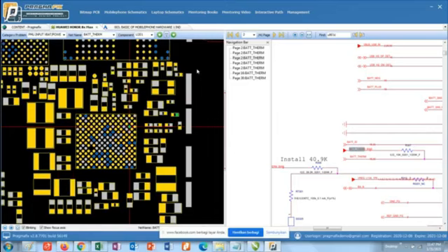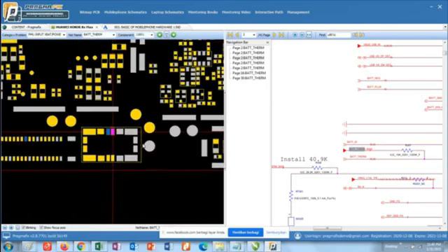At that time the NTC thermistor is connected to the ground, because NTC means negative temperature coefficient of resistance. As the temperature rises, its resistance drops, so it will be more connected to the ground. So the battery connector's temperature line will be connected to the ground in the battery. That's the meaning of NTC, or negative temperature coefficient.